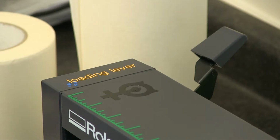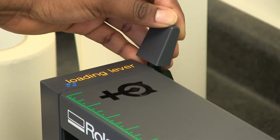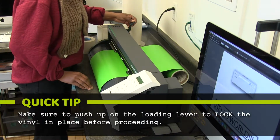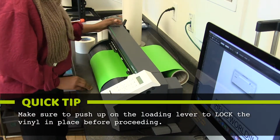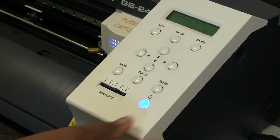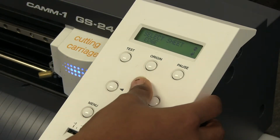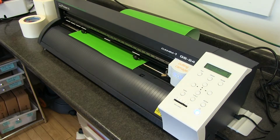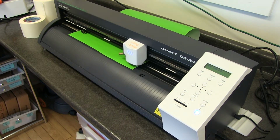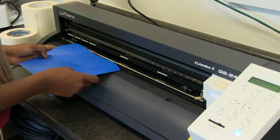When the loading lever on the left of the machine is up, the material is locked. Down is unlocked. Clamp down on the piece. Turn the machine on to scroll through the options. You'll use Roll to cut on a roll. Press Enter to accept the roll option. Check again if your material is loaded correctly and parallel to the guidelines. Now you are ready to cut.